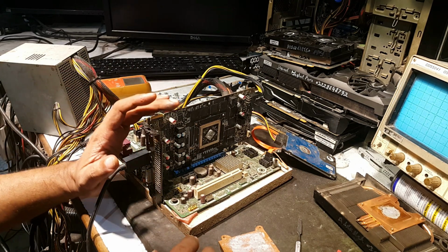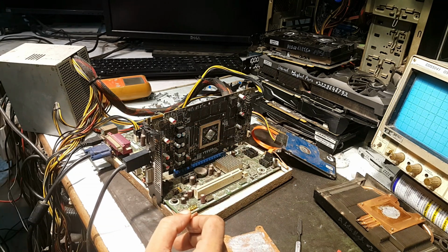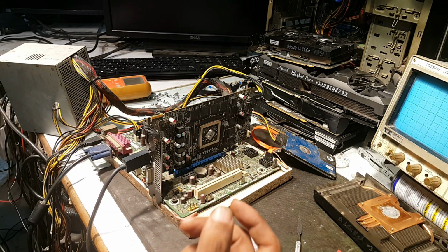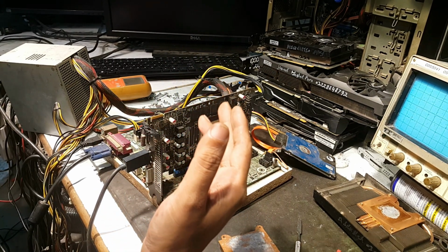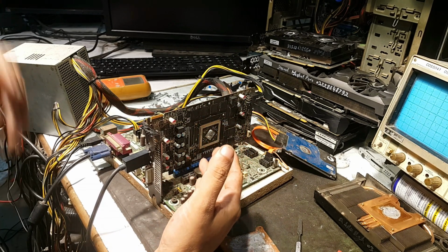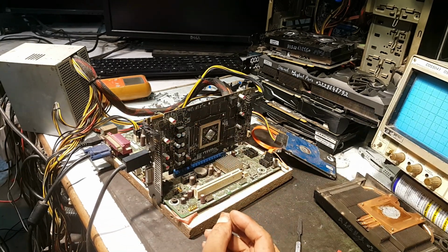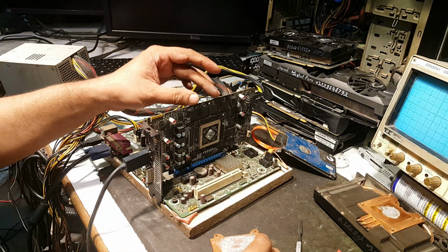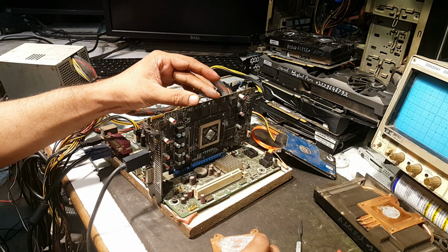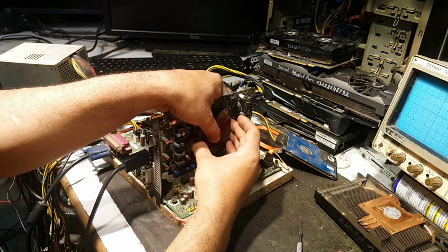I have just washed this GPU chip, and now I'm going to test it again just to verify whether there is any kind of change in the display. Maybe the fault has been rectified. But even if it is rectified, we must still reflow this chip, because the rectification of its fault may be temporary, so we have to reflow it. Just check it again.